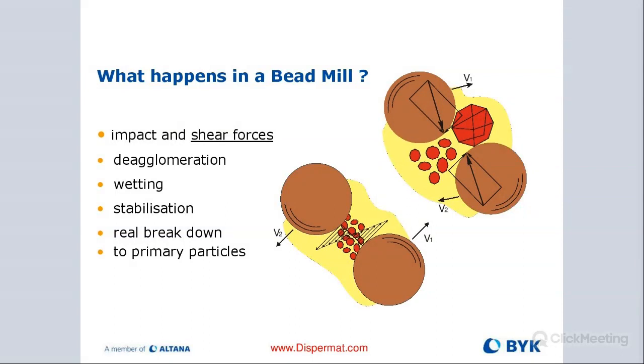We're not trying to crush our pigment particles. We're only trying to break up these binding forces. That's really all that we are trying to do. Actually, the probability of a pigment particle being wedged in between two beads at the same time when they're colliding is very, very slim, because of the fluid dynamics that push them away. So really, that pushing action is the force that's causing the breakup of these binding forces. That's what's really happening there.